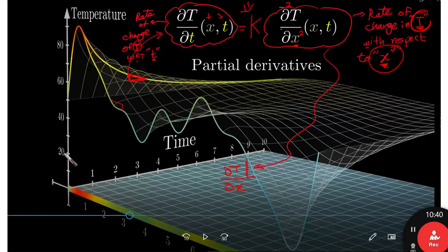So this is the point that I want you to understand: the rate of change of the temperature at a certain point on the x-axis is going to be related to the rate of change of temperature with respect to the distance on this bar, but it is actually related with the second derivative, partial squared t partial x squared.